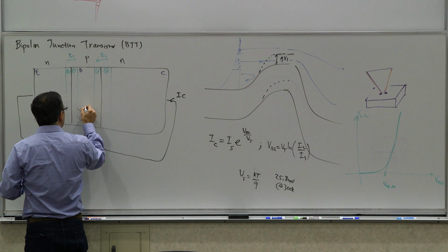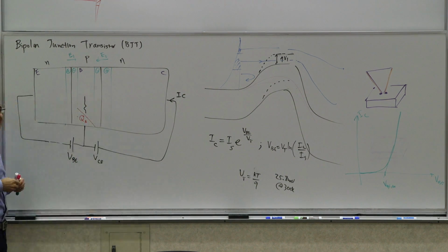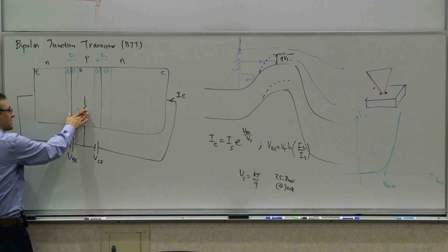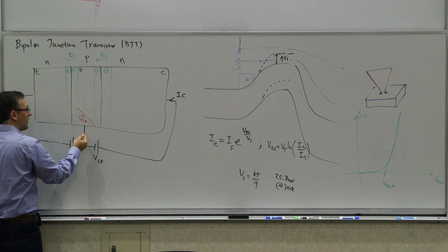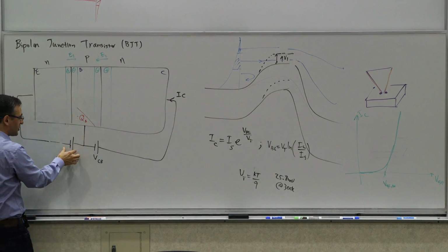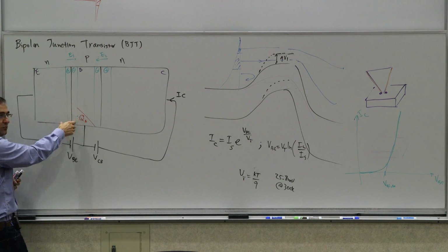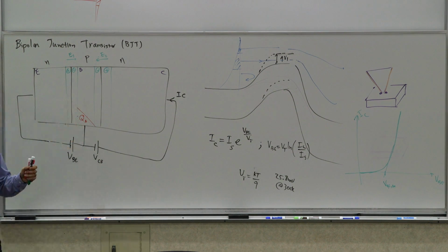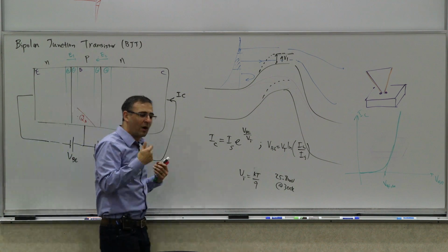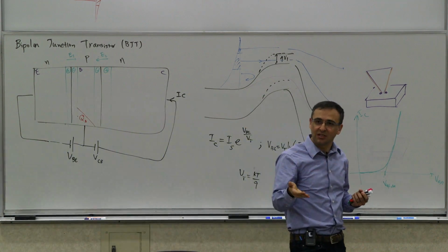It will keep increasing. And that can get in the way, because if you have a series resistance where there's current flowing, then you will have voltage drop. So some of your voltage drop is not really dropping across where it should be. It's dropping across some resistor, which is not going to be used for controlling the device. So you lose some of the control, some of the sensitivity of the device.